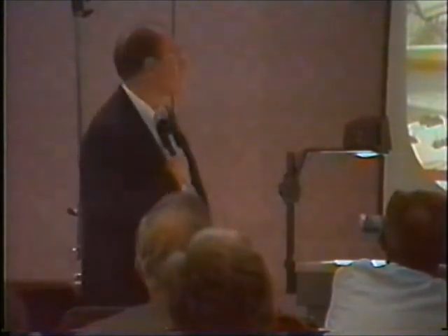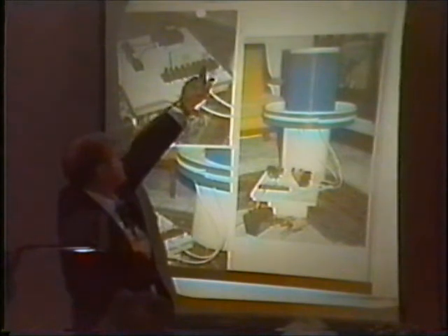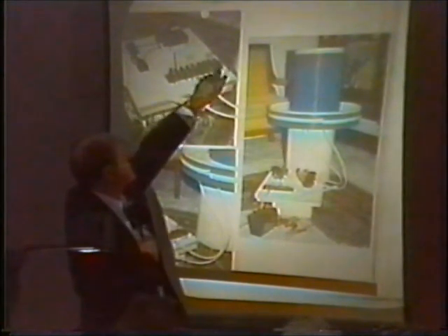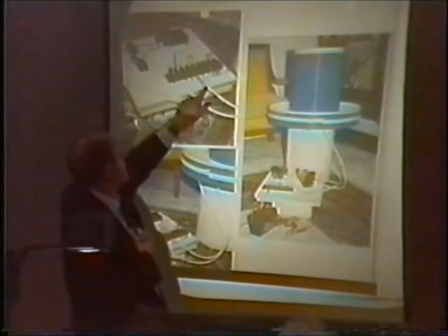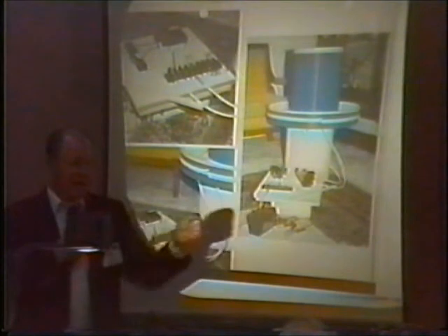I couldn't understand. On the terminal block, what is the small orange and yellow mechanism? A small orange and yellow. Actually, what I've done here, you can't really see it, but I've got a circuit going along here with a capacitor on it and a resistor, and I folded it back. Instead of having a series thing looking at you that would go out like this, I've gone down, skipping the contacts there, and then I've come back to a certain point. So I've got a resistor and a capacitor in that deal.